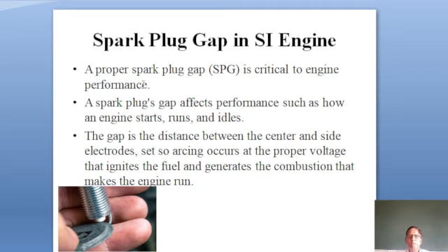At the same time, if the spark plug gap is too low, that means the spark generated is very weak, and it may not burn the air fuel mixture completely, and that is why unburned fuel may come out of the engine, and the efficiency of the engine is not properly attained. So maintaining a proper spark plug gap is very important.